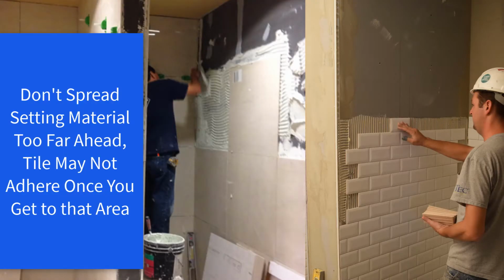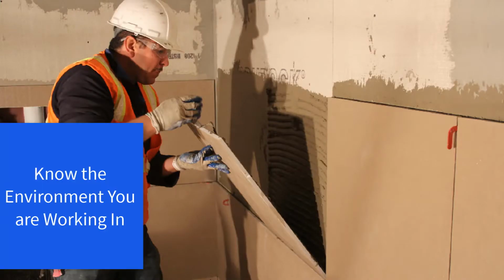Do not spread the setting material too far ahead, as it can allow skinning or overglazing, which will not allow the tile to bond to the mortar. Be aware of the environment and room conditions, as skinning of the setting material can occur more quickly in areas that include high temperatures and low humidity conditions.